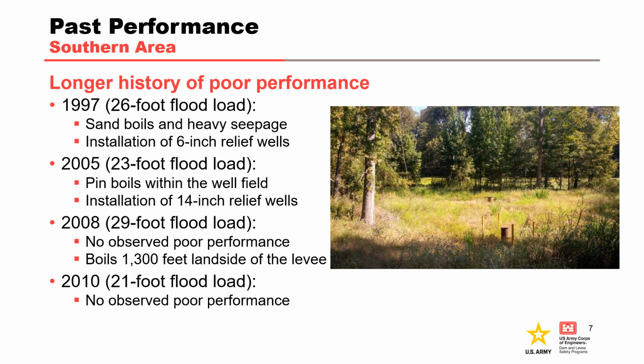Poor performance in the southern area dates back to the flood event in 1997 when the levee experienced a flood load of approximately 26 feet. During this event, sand boils and heavy seepage were observed on the land side of the levee. This prompted the installation of six 6-inch diameter relief wells in the vicinity of the boils to reduce foundation seepage pressures. In 2005, with a flood load of approximately 23 feet, several pin boils, by definition less than an inch in diameter, were observed in the relief well field.